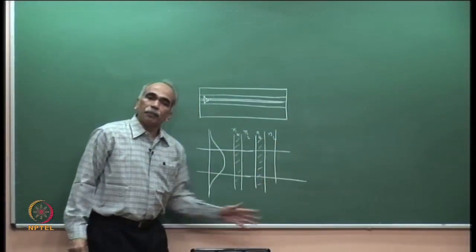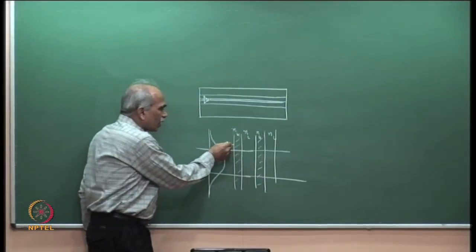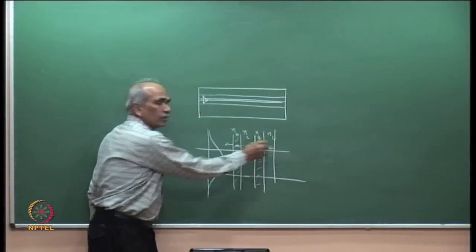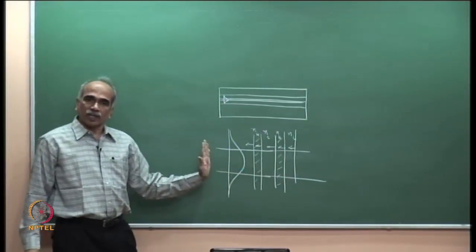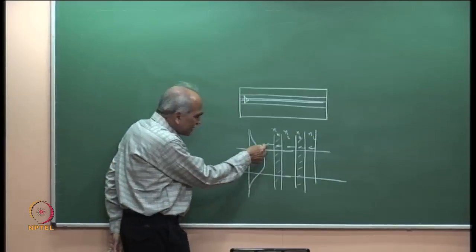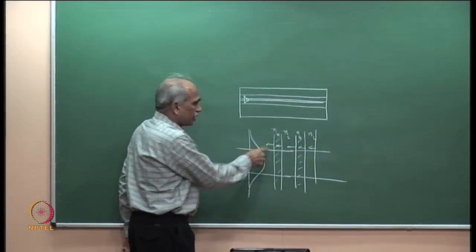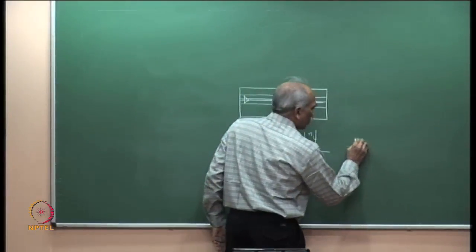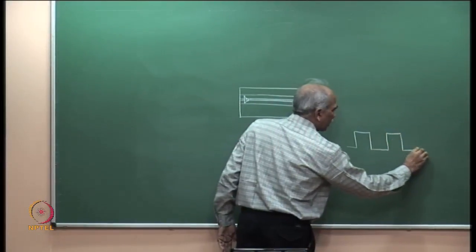It is having a periodic reflection. So, the mode is undergoing periodic reflection at the interfaces like this. The mode is continuously undergoing periodic reflections as it travels in this direction, which means it is getting reflected at interfaces continuously. For simplicity, I will show this as a step variation. So, let me show the refractive index variation like this, step variation.